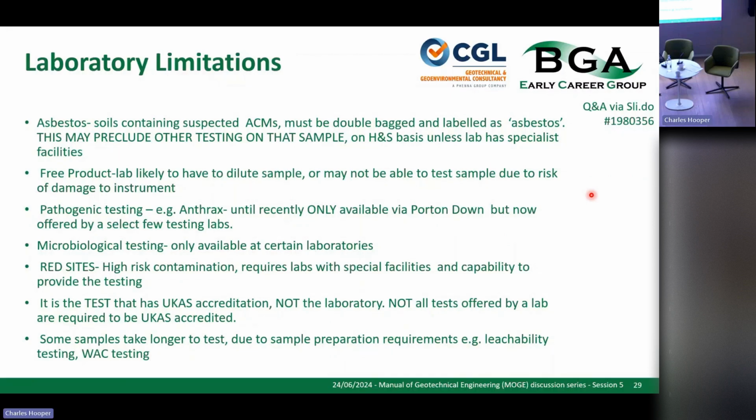And just be aware how long samples take. Quite often you'll have a client that says, "I need these results tomorrow." Yes, you can pay money and speed them up through the process, but you can't speed them up quicker than the test takes. So if you want leachability testing, you're going to need 48 hours to put it through the sample processing. Doesn't matter what you pay them, they can't physically do it any quicker. So just be aware that you don't overpromise to clients, saying oh yes, we can rapidly do that test, we'll do it within 24 hours. Some of them they just cannot do. It's knowing what the limitations are.